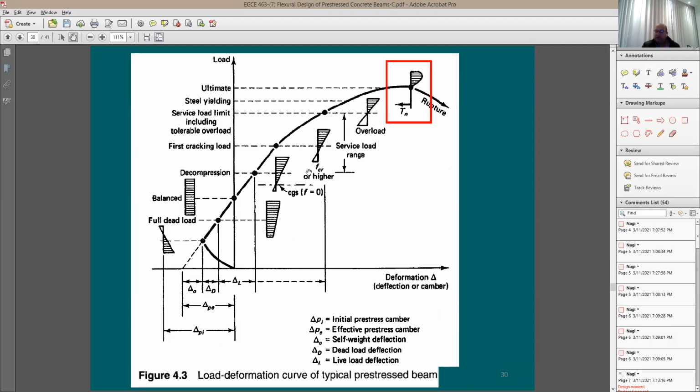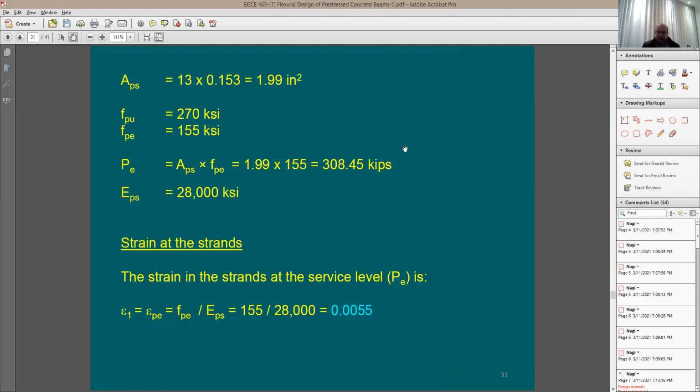The point that we're interested in this case, we're not interested in during rigging or moving the beam. We're not interested right after the pre-stress. We're not interested in checking the service load case. We're interested in the capacity. So we're right here at the last point. So we're not doing here any of the checks that we used to do. We're just after finding out the capacity Pmn of this beam, which means this distribution of forces.